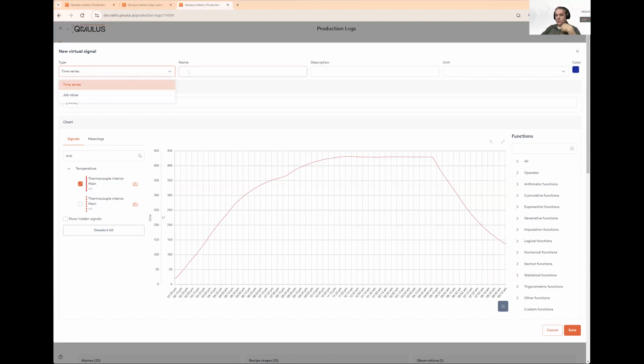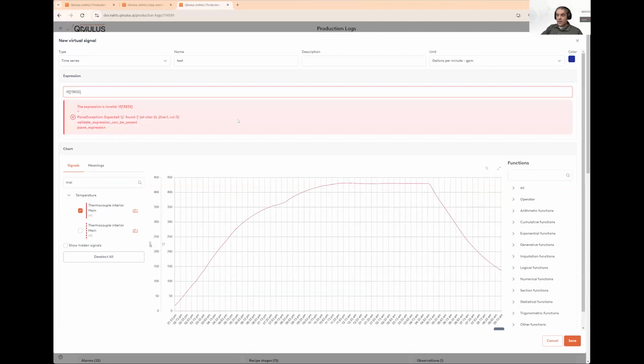Now, that basically explains this. I'm looking for now flow. So this is like a mass flow controller, dare I say, for water. So let's just make this test. I have here a liters per minute, or I have a gallons per minute, right? I take a gallons per minute, and I have now this device here is temperature. You and I know that, but I'm going to make a small, very simple formula. If that temperature is greater than 150 degrees C, then it's 1.1 gallons per minute, else 0, close.